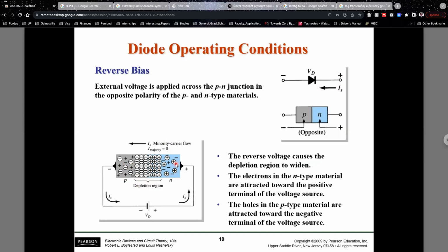What we had said earlier is that because of the inherent properties of the atoms in the depletion region, in the P-type semiconductor you had these negatively charged atoms, because you had an abundance of holes which are positively charged, which means the atoms themselves will be negatively charged to maintain electrical neutrality. Now, these negatively charged atoms on the P side will repel the majority carrier electrons inside the N-type region. So all the electrons will be pushed towards the right-hand side.